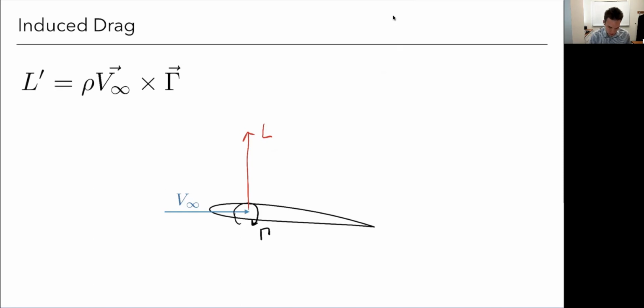All right, so the problem is though, remember last time we talked about this downwash. The airplane is flying straight with v infinity. So from the perspective of the airplane, the wind is coming in straight at v infinity. But because I'm generating lift now, I'm actually pushing air behind me, starting at the plane of the plane. In the geometric plane of the aircraft, I'm already starting to push air downward. So there's actually this downward component of velocity, and W is just the symbol we give for downwash.